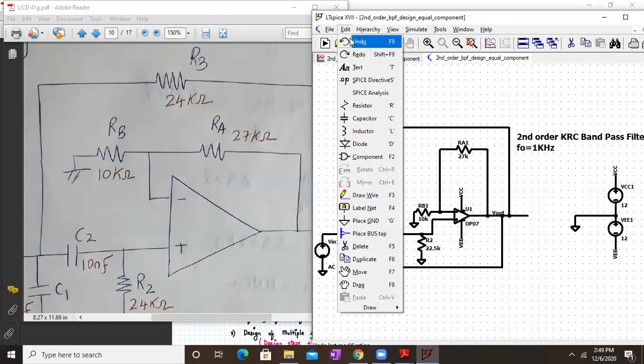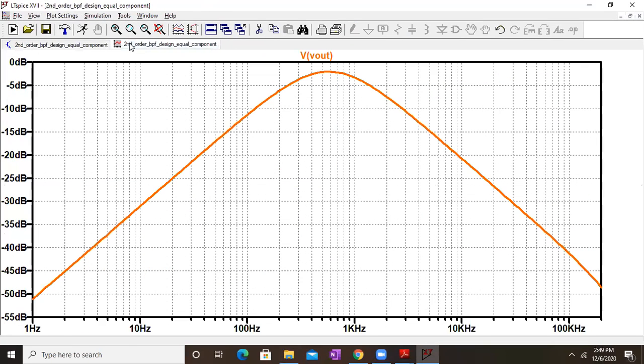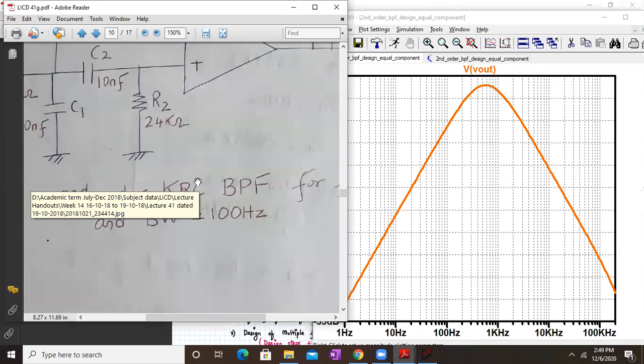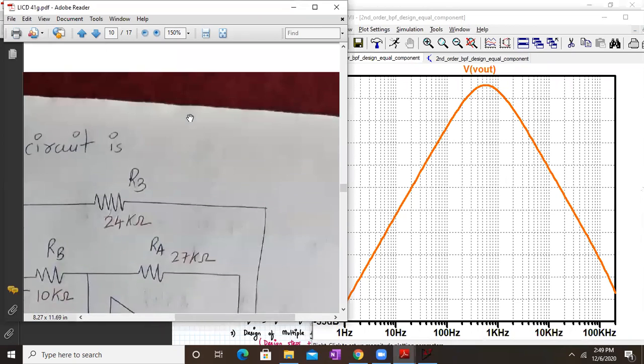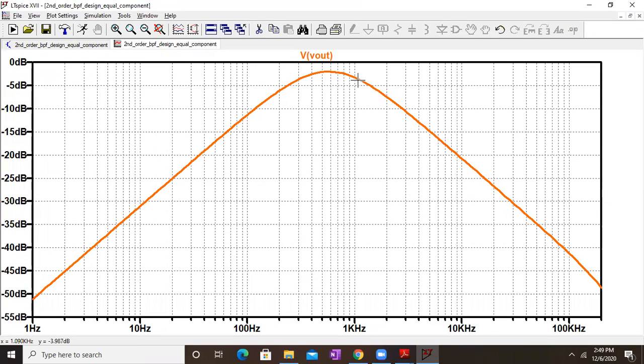What I was trying to do was check whether the cutoff frequency range is properly coming or not. Over here, the highest frequency will be my resonant gain. At 1 kilohertz, I'm getting it over here. It's slightly less, but nevertheless. Let's check that number once. Okay, it's definitely behaving as a bandpass filter, as you can see very clearly.